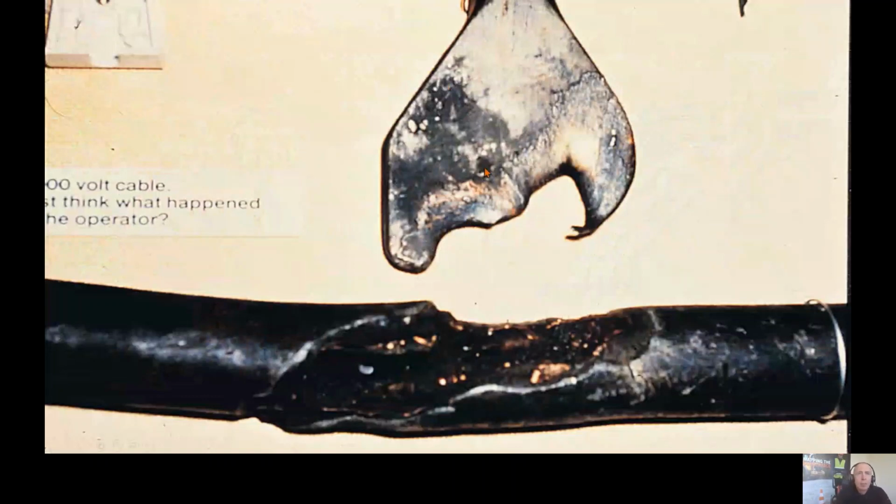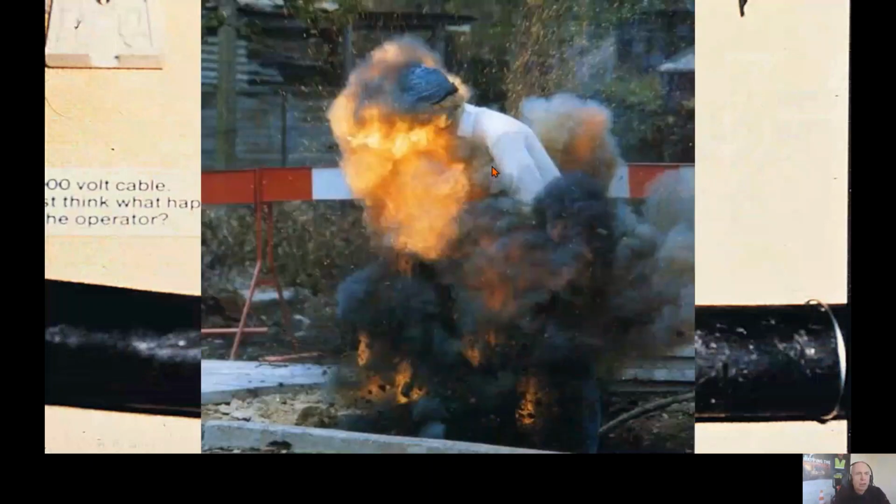These are not bits of weak metal. They're quite strong, toughened metal, and you can see how it's gone across the cable there. And these two sections here is actually where you've shorted out two of the cores, and the short circuits happen there, and the current's built up, and in effect, a massive arc welder in a way has melted down the cable, etc. And that's the explosion that can potentially come from even low voltage power cables.